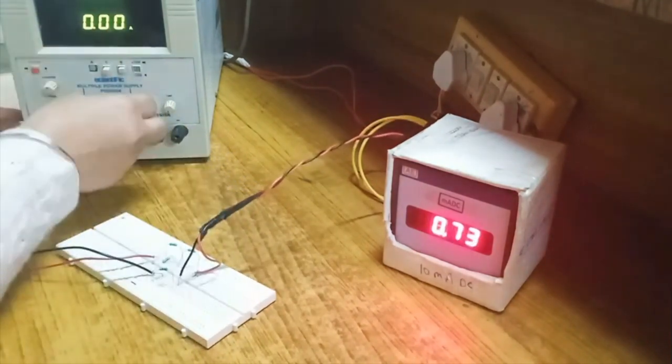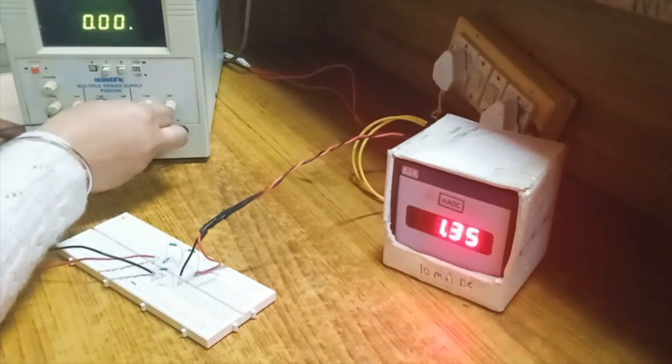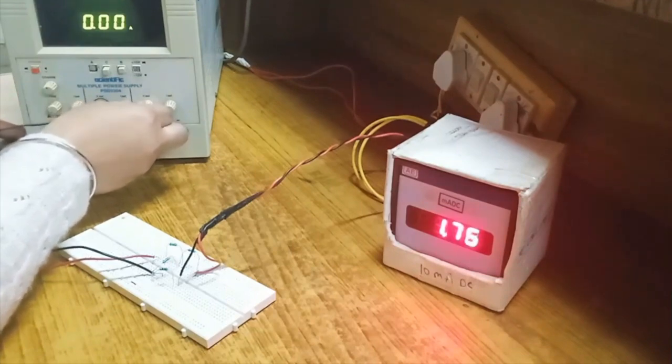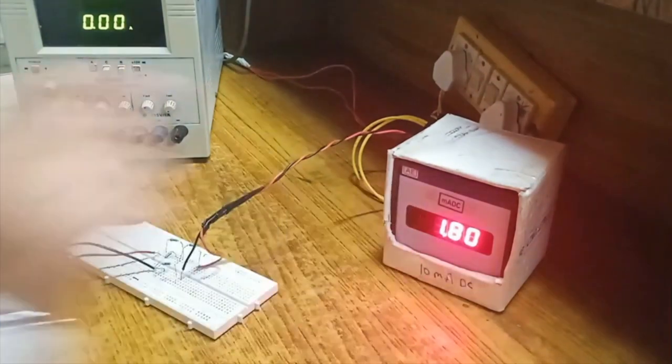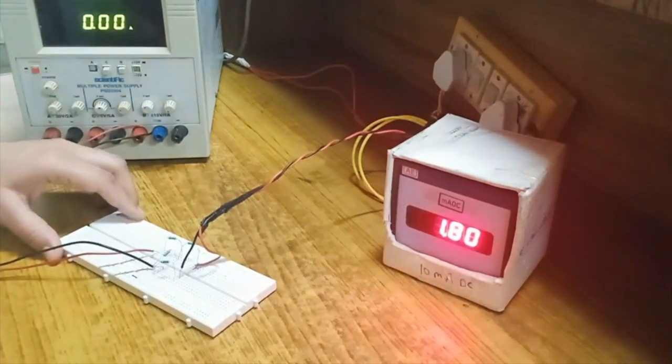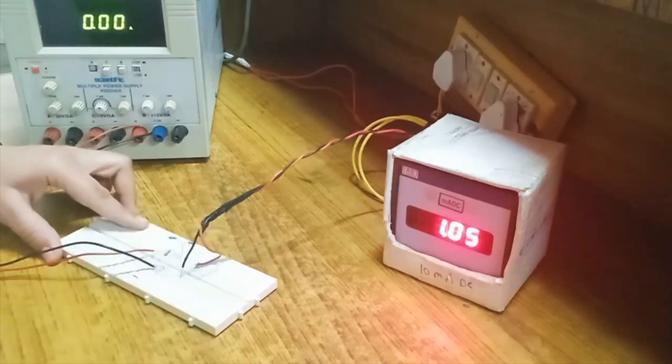Let us set the input voltage to 5 volt. So we have got 1.8 milliampere IL, the first circuit diagram. Second circuit diagram is remove RL. So this is our RL 1 kilo ohm. Remove RL and calculate short circuit current.